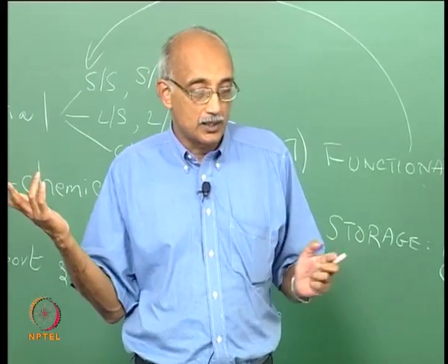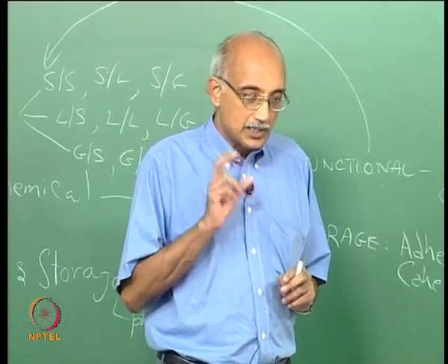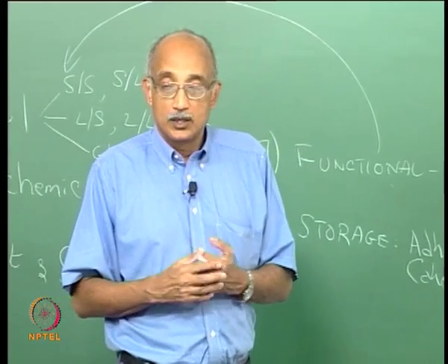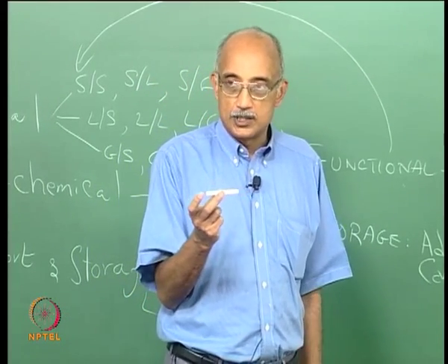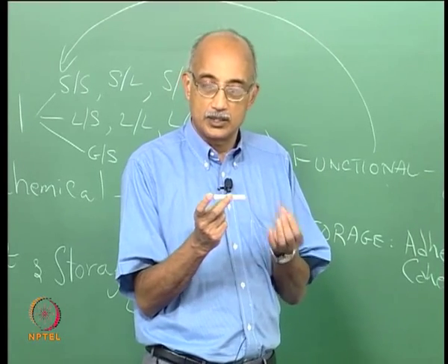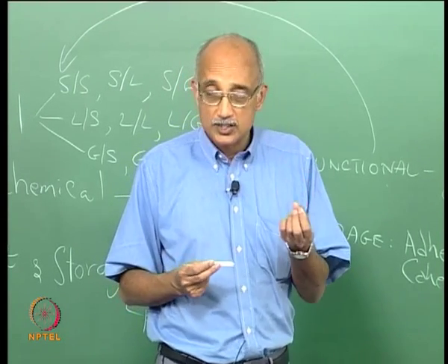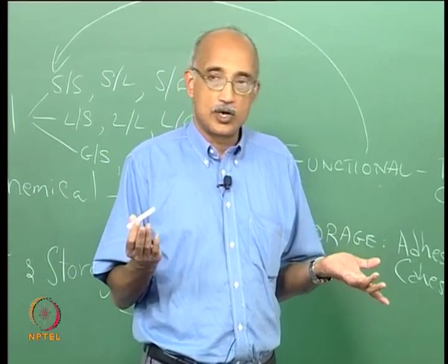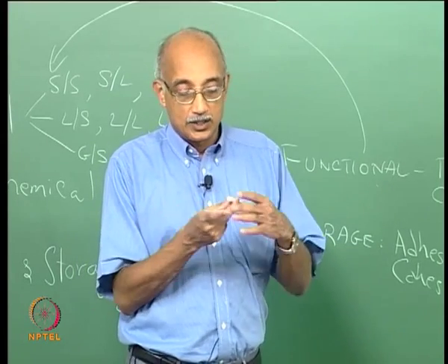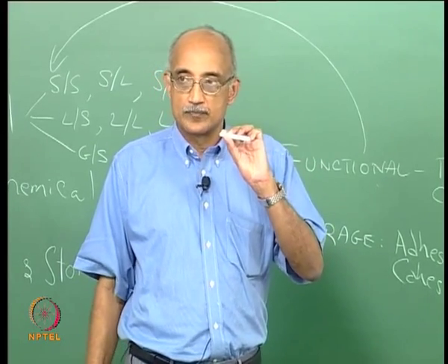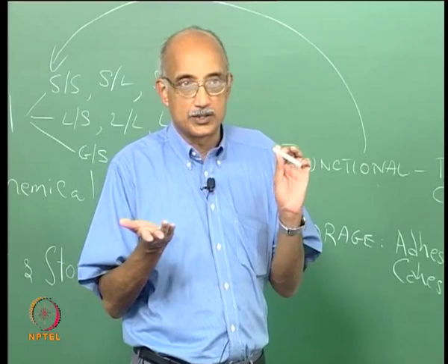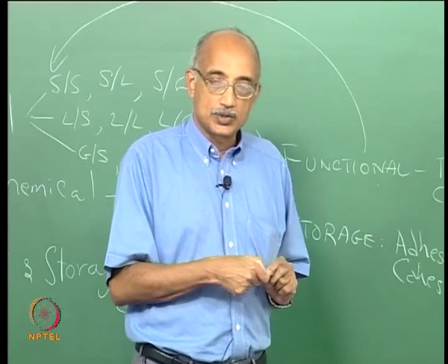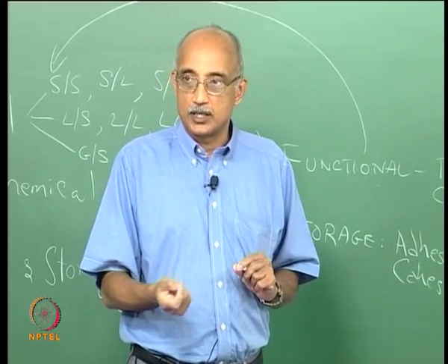Size analysis, again, we will see that size is not an absolute measure. Size is always relative to something. As the object gets larger and larger, the uncertainty in size measurement decreases. As the object gets smaller and smaller, the uncertainty in its size measurement increases. It's essentially a signal to noise ratio. An object like this has a large signal that it emits from its surface, and the noise is very small. The noise is kind of fixed. But as you can imagine, as a particle gets smaller and smaller, the noise will become comparable to the signal and even start exceeding the signal in many cases.